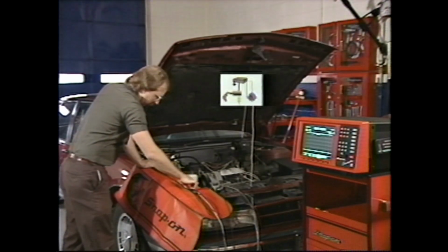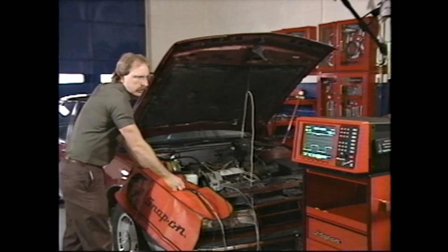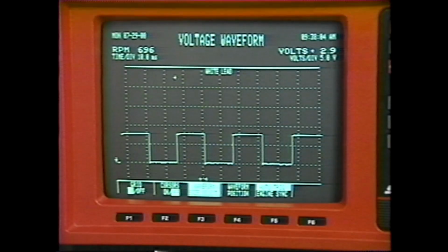Some signals are generated voltage, while others are modifications of a reference voltage, which is supplied by a voltage regulator in the computer. Usually, signals are predictable repeating patterns that occur consistently in a certain time-volts range. Most signals occur in the 0 to 5 volt range, much smaller than the 12 volt supply from the battery.